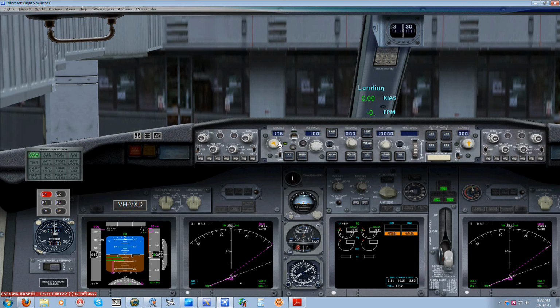So there it is, 196. Okay, don't worry about the auto throttle for now. We'll put that on prior to taxi. Indicated airspeed, again we changed that to 240, so you can use the right mouse button to change that all the way up to 240. There it is, so we set that for 240.